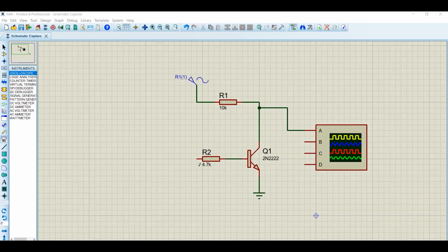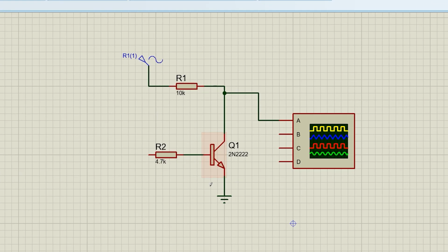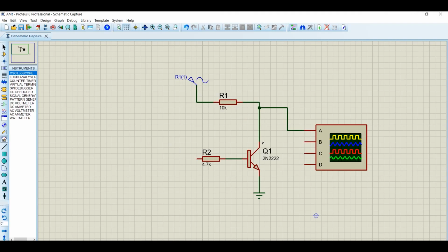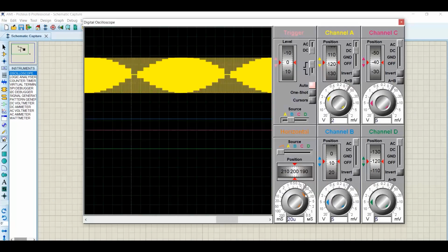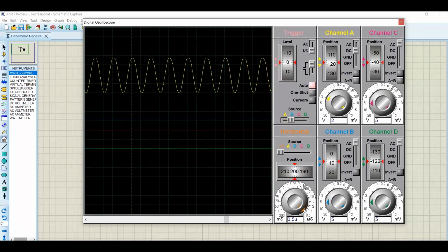Alright, as you requested, I'm going to demonstrate AM modulation using simulation software. This simulator is Proteus, which is more accurate than others like Multisim, and most electronics experts prefer it. Now take a look at this circuit. If we connect the carrier signal to the collector of a transistor through the resistor, we will see the exact same signal at the output because the transistor is off.